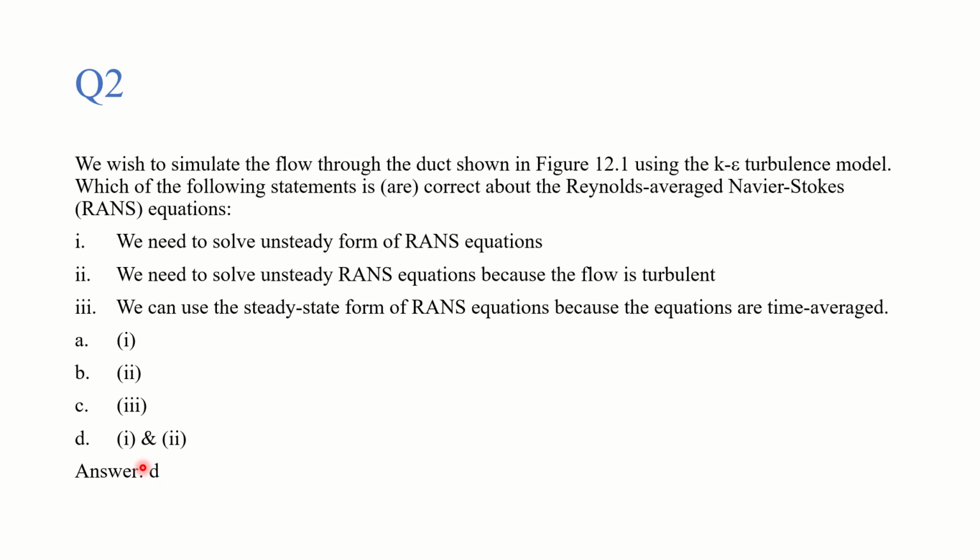Here we do Reynolds decomposition, where an instantaneous quantity is decomposed into time averaged and fluctuating parts. If there is turbulence, there are so many fluctuations, so to deal with that we decompose it into the time averaged one plus the fluctuations, which gives the instantaneous value.